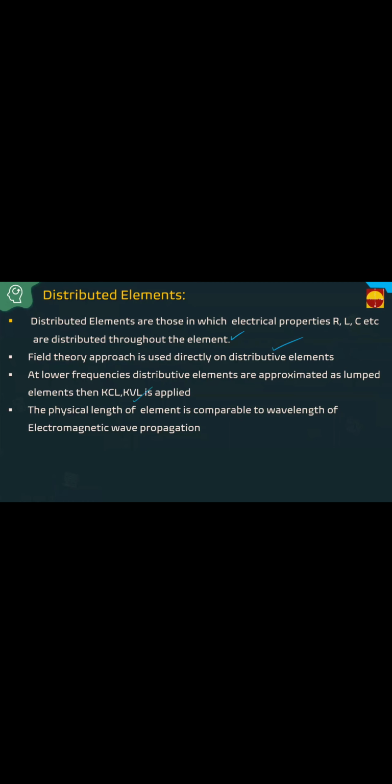KCL and KVL are applied for low frequency. We can apply them for distributed elements if you assume that the distributed element is approximated as a lumped element. But that is possible only for low frequency. At higher frequencies, we can't approximate, because the physical length of the element is comparable with the wavelength of the electromagnetic wave.